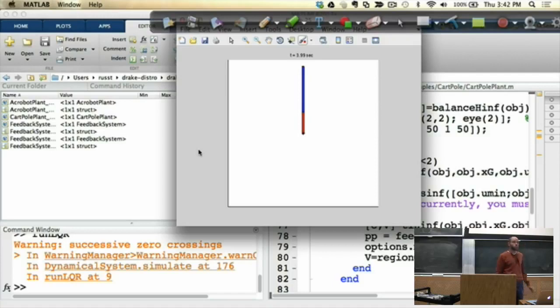Yeah? So what prevents you from just having different linearizations for different parts of the system and trying to mesh them all together? That's what we're going to try to do. And that's why there's a TV LQR, because the problem is that if I pick a linearization over here, it's not a fixed point of the system, so it's not linear dynamics, it's affine dynamics. The system, even with 0, is going to move around. So we have to do something a little smarter, but that's where we're going to get to.